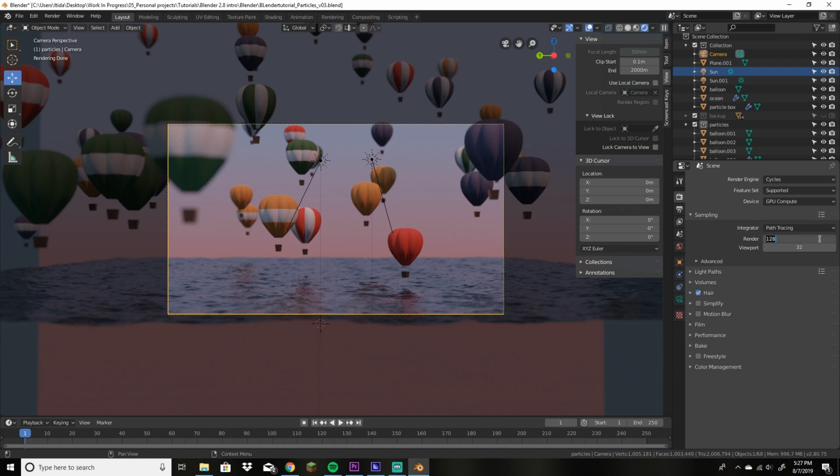Let's see, sampling. You can test what your computer needs. Whenever I use depth of field, I tend to get some weird patterns in this area. Like, see how it's kind of grainy now? We're going to use a denoiser that's going to help with that, but that can only do so much. So I would start with probably around 400 as your samples, just because we're using depth of field. With a denoiser, if it was without the depth of field, you could probably get away with 200, but this should work fine for me.